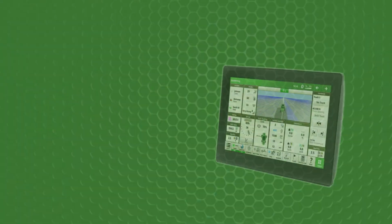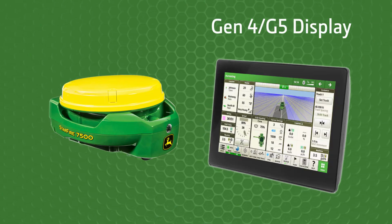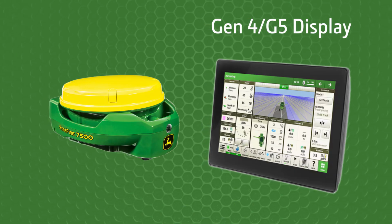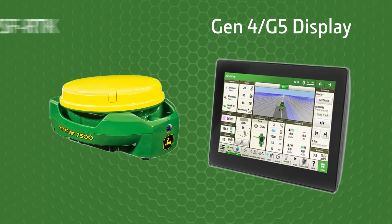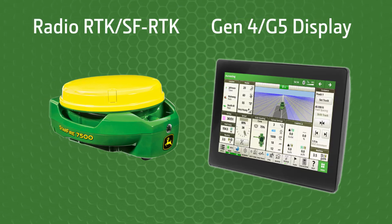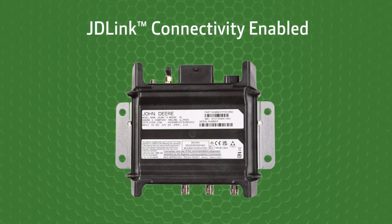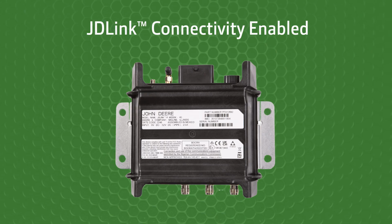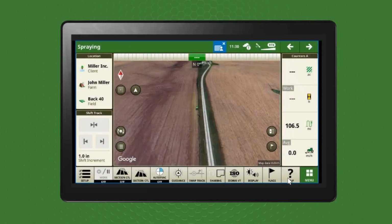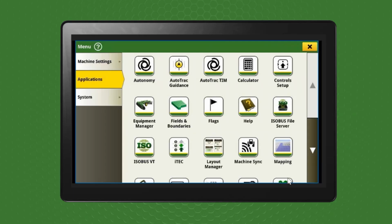You will need a display and receiver. It is recommended to use a Gen 4 or G5 display operating on the most up-to-date display software version, as well as a Starfire receiver with radio RTK or SFRTK correction mode. Note that connectivity with an active modem or MTG is also recommended for seamless transfer of your boundaries into Operations Center.